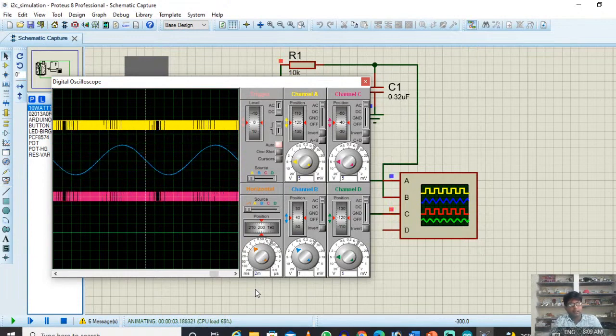And if I filter the pink color one, you will get that blue color. Similarly, if you remember our motor control, there is an inverter. In that inverter, if you give this kind of PWM signal to the top and bottom leg, then finally we will get that output.